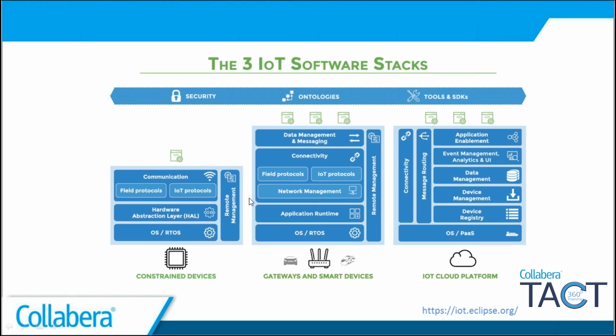There is a question from Rajendra again. We have sensors. However, can we find out they are working all the time? Is there anything like heartbeats? Yes, Rajendra. We can have intelligent algorithms running on the sensor nodes to send pings or periodic messages to tell us that yes, the sensor is okay, and sensors can even send us messages if they are faulty, right? So we can have a kind of analytics deployed on the device end, and that analytics or intelligent algorithm capable of analyzing the signal or data coming from the sensor could